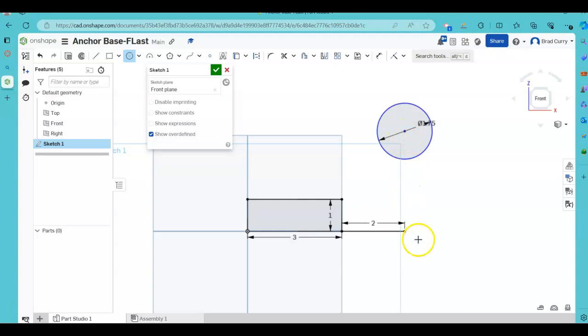It's really constrained to the end point. So if I were to come in here now, let me escape out of that drawing tool. If I were to change this to 1.5, that moves it, because I've constrained this to that endpoint. So we have to be aware of what these constraints are. In this case, we'll keep that at 2 inches.